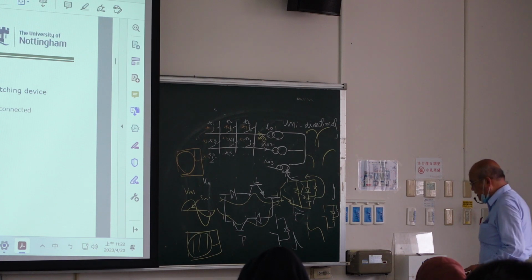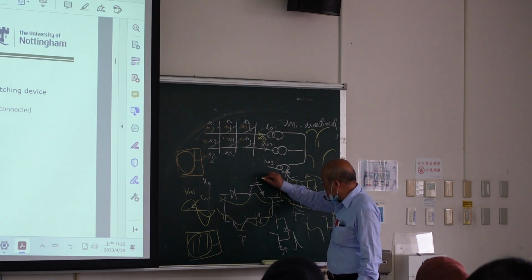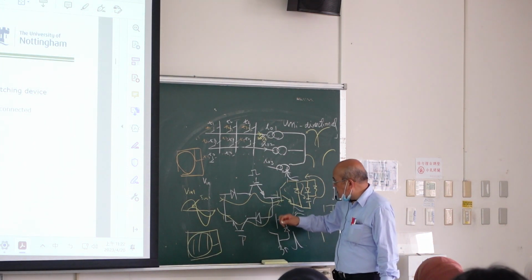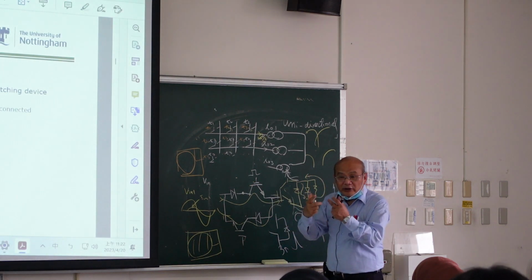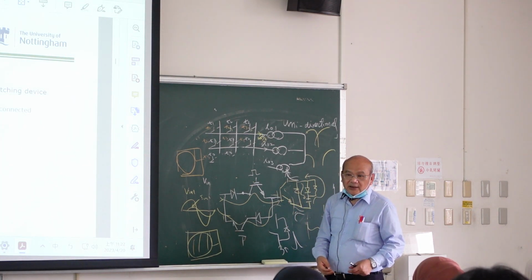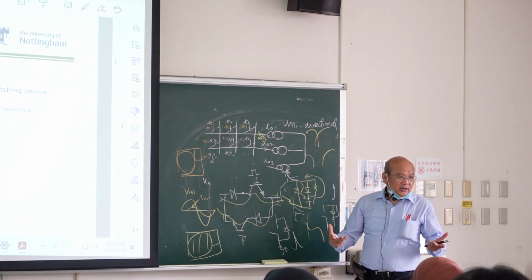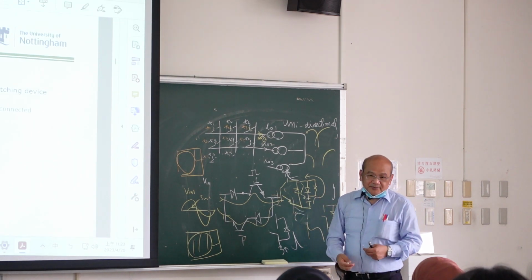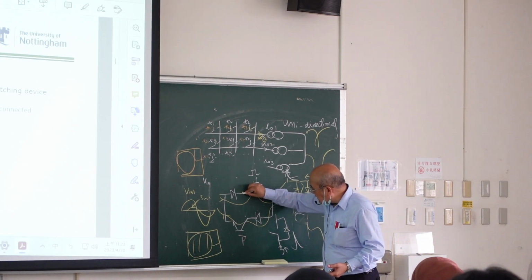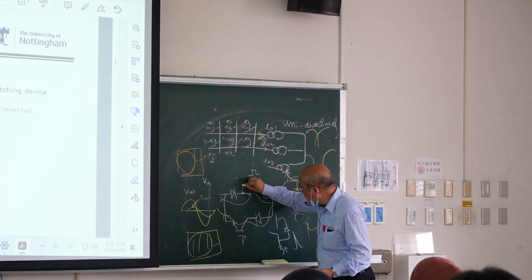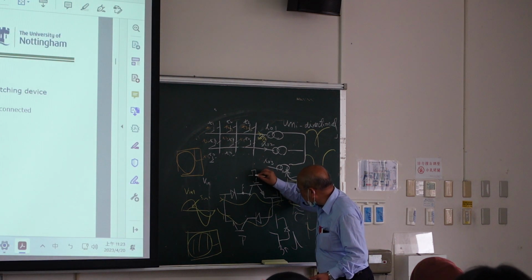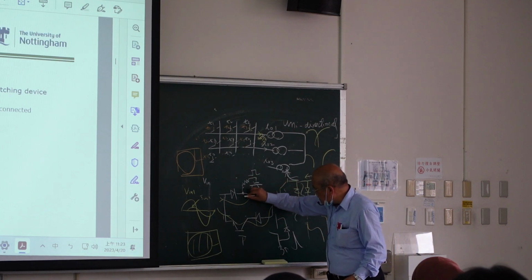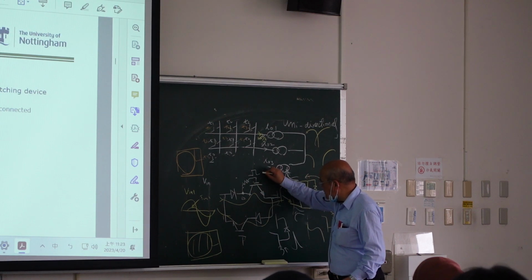If you have an IGBT, you need to trigger the IGBT. So you have to put a gating signal here, right? If you have a gating signal, you have to get a ground reference, right? Otherwise, you have no reference. If you have no reference, how can you drive the IGBT, right? So you have to get a reference here. So maybe here I need a reference. So I need a resistance to say this is ground and then this is 5 volt.